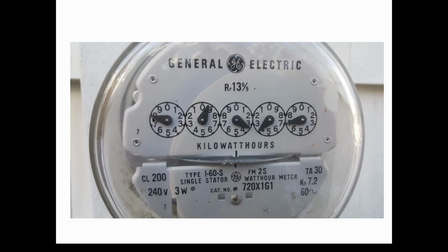Now, you may have an electronic version which has a digital display, and it's probably a lot easier to read. You can probably press a few buttons depending on the meter and show exactly what the usage is. I'm going to talk about this mechanical one because it requires a knowledge of how to read it in order to get the numbers. The other ones probably come right up and show you directly. So for this meter, as I said, there's 5 dials here. And each dial provides a digit, and it's measuring kilowatt hours, okay?